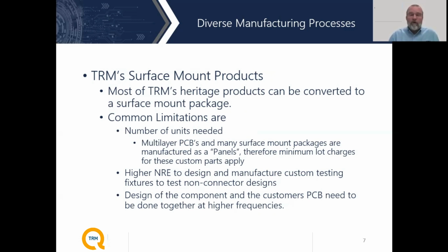Directional couplers, power dividers, these sorts of devices can be built using multi-layer technology in a bonded assembly, utilizing plated through holes and embedded resistors. So we certainly can take virtually any one of our products now and repackage them into a surface mount package.